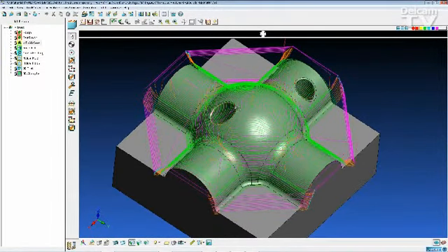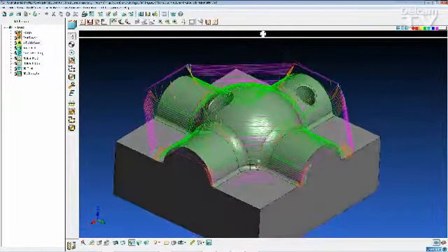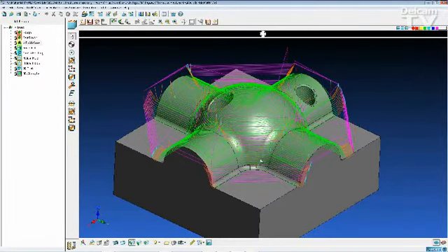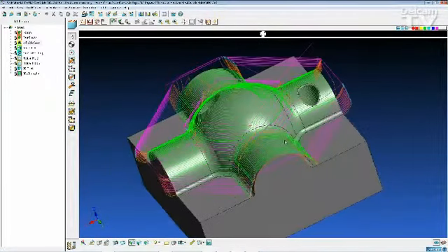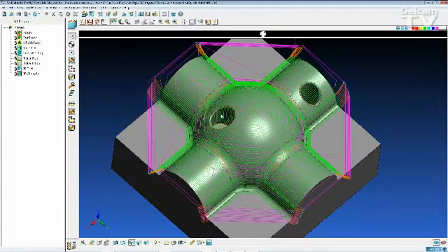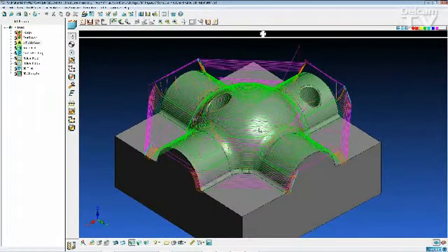So there's the surface machining toolpath, spiraling around, doing the 3D offset, but doing Constant Z on the walls which are more vertical. And there's an overlap between these toolpaths. And you can see the holes are machined right over top of them as if there's a smooth patch and the holes aren't even there.